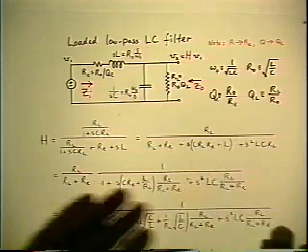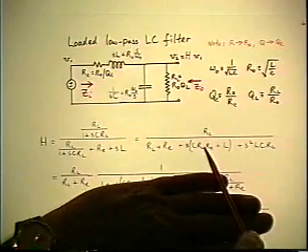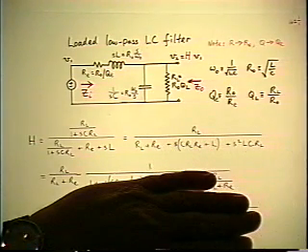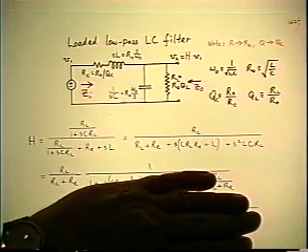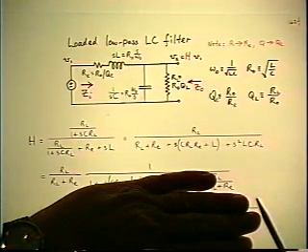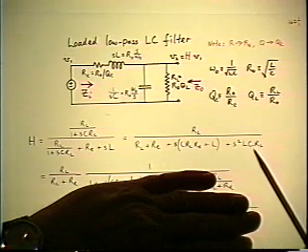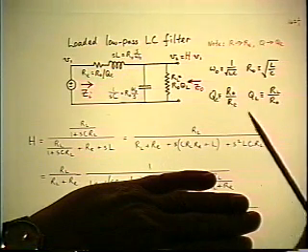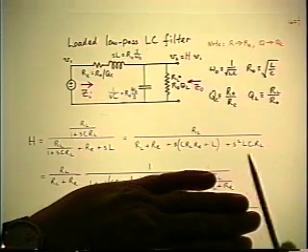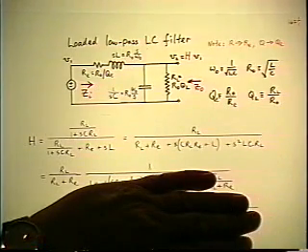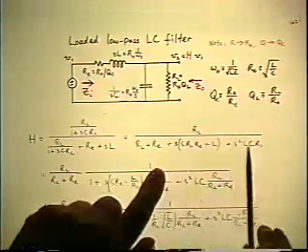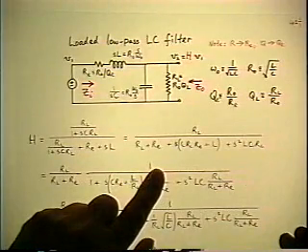And most people would stop at this point. Say, this is the answer. Of course, it's correct, but it doesn't much help. Because what you don't get from this is the fact that the loading does three separate things, two of which are second order, and the third one is this most useful result of all of this: the parallel combination of the Q factors. In this version, you don't even see any Q factors.